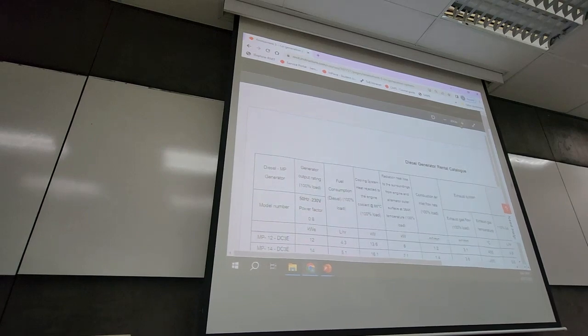the coolant heat exchanger, water coming in at 20 degrees Celsius, goes to the exhaust heat exchanger. And then comes out at 85 degrees Celsius. So that's your generator, diesel generator. 85 degrees Celsius out of the diesel generator, back into the diesel generator at 35 degrees Celsius. Q dot is given in that column.